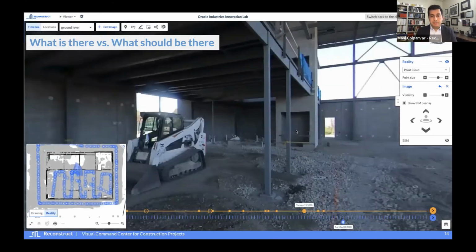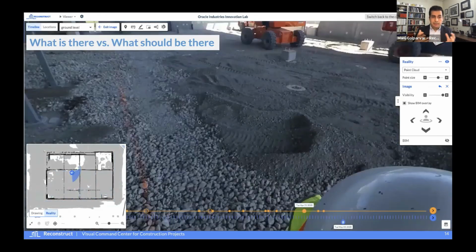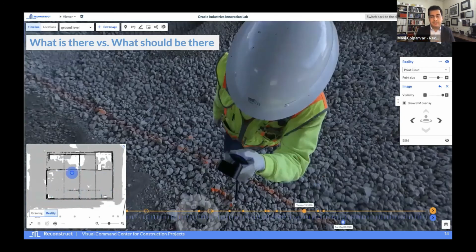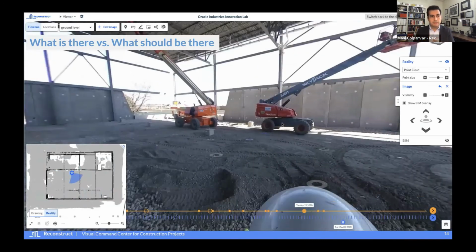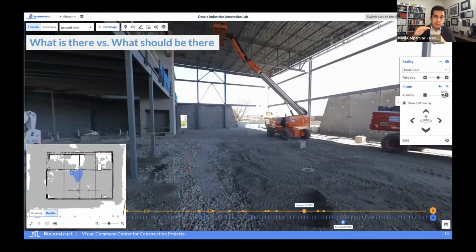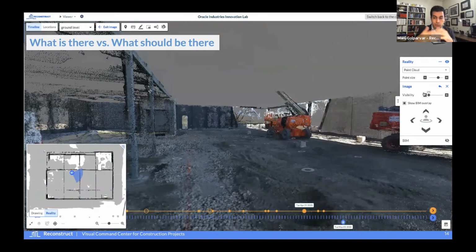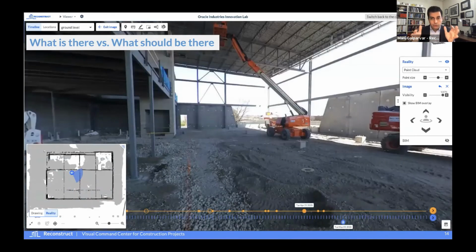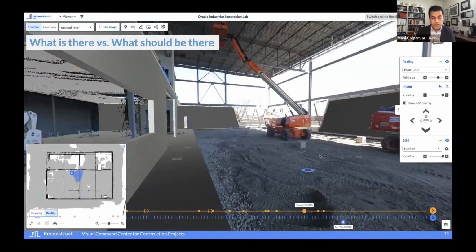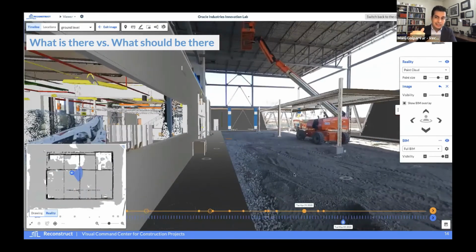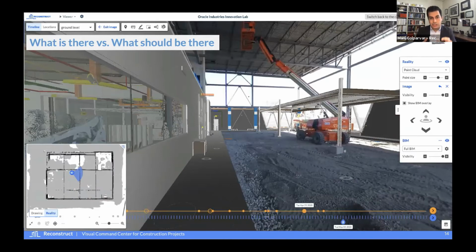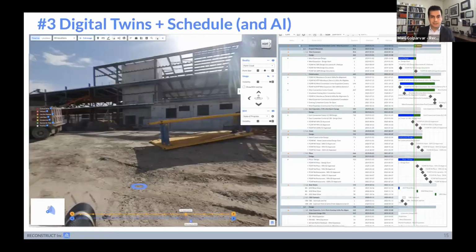Once you have these capabilities in terms of being able to videotape and map the job site in 3D, have that navigation map, you can always jump into any location you desire along the project timeline. And you can say you want to filter the data to ground level. So that point cloud, the image only shows you things that are relevant to that location. And then you can superimpose your design information. Also see that design segmented to that location. So you see the design of what should be there versus what is there on the job site.